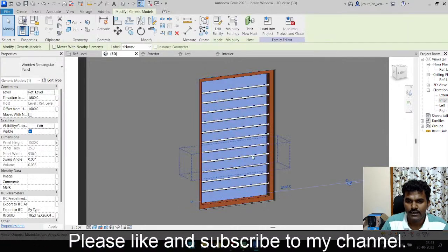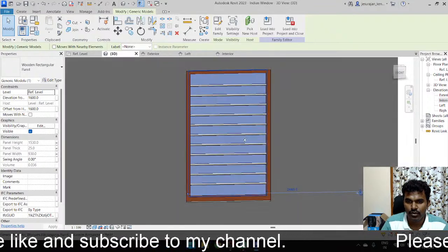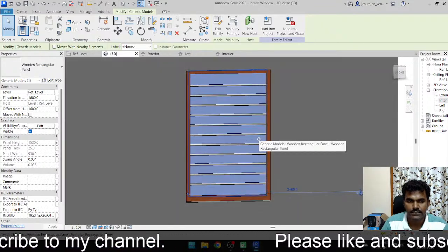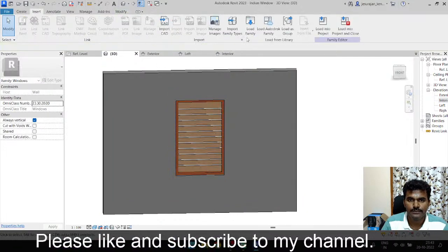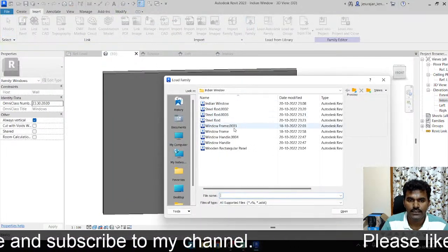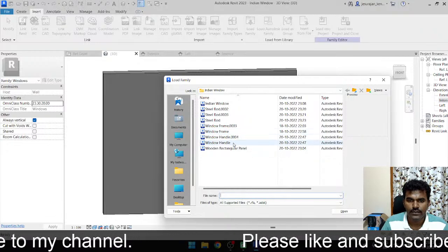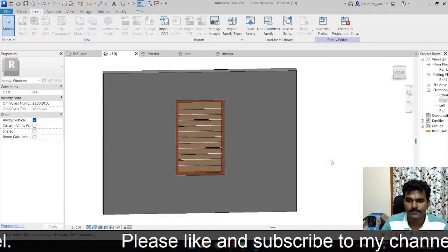Now what do we need? I need to fix that knob just here in the center. Okay, so now just load the knob. Load family, select window handle, open.